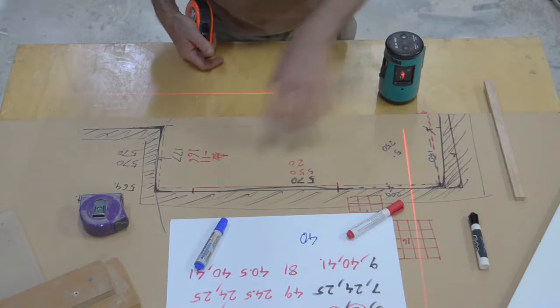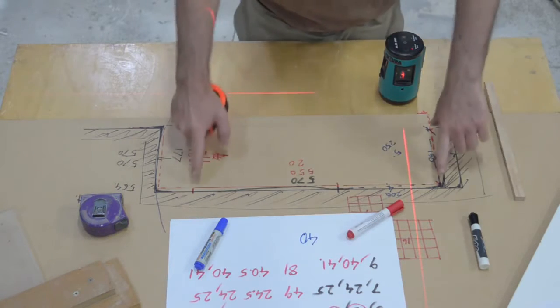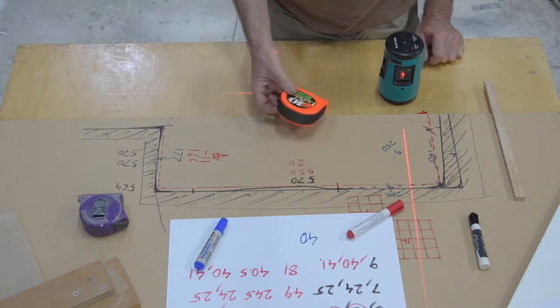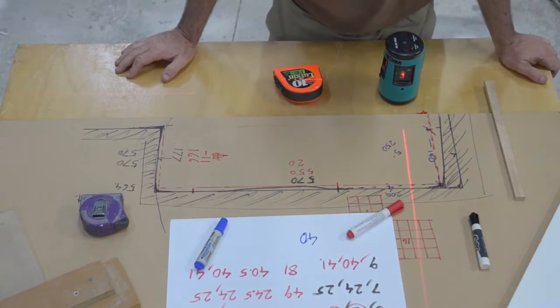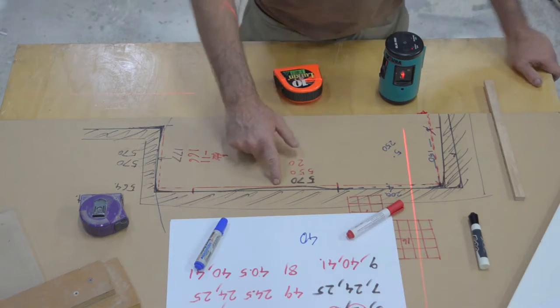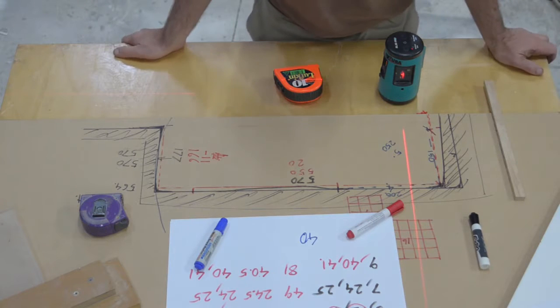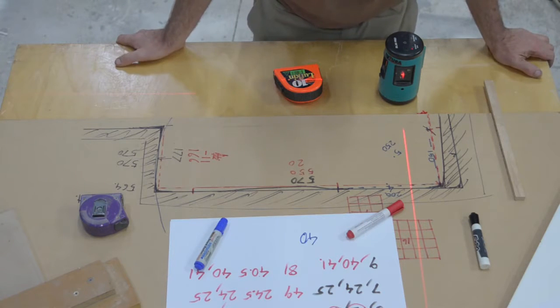If you don't have these tools, you can use this method with the various triangles and a tape measure and your tool to mark with to establish a square, or you can simply build in ample tolerance, like guess that 10 millimeters is the gap, and so we're going to allow, say, 20 just to make sure it's safe. So they're the three real options. Either measure it well, so you know your numbers precisely, but if you've got the tolerance, just use the tolerance and create tolerance to make life easier.